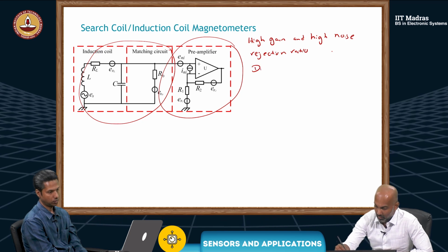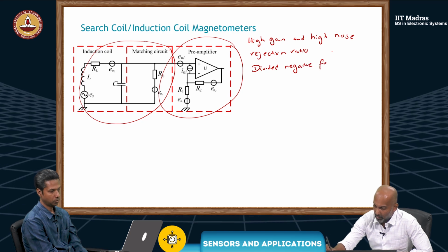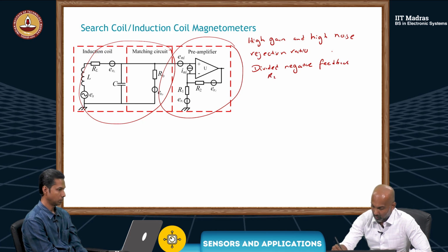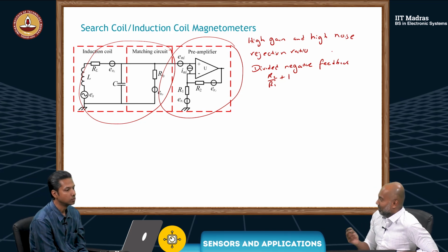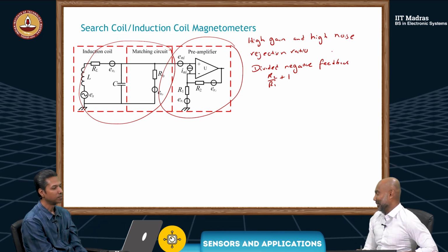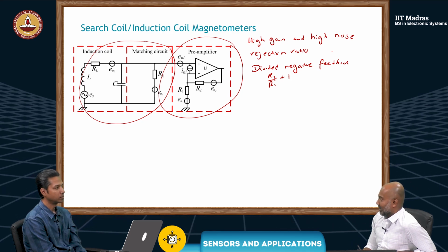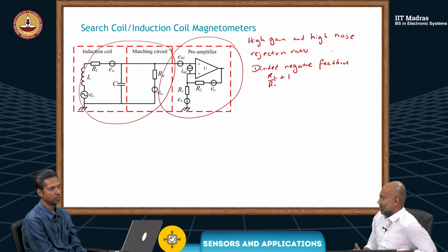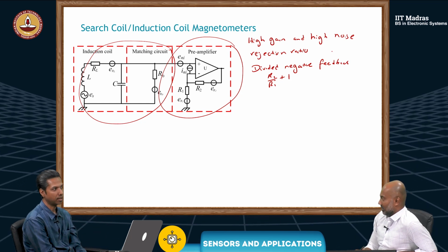Now here we have a divided negative feedback. So your output will then be R2 over R1 plus 1. But Bobby, you work with plenty of amplifiers. Tell me, what's the problem here? When you connect your amplifier, there's also maybe some noise. There will be some noise introduced by the components and ICs in the amplifier.